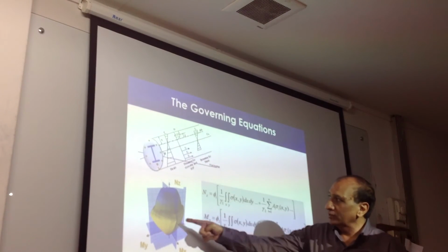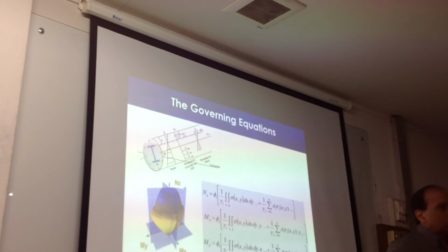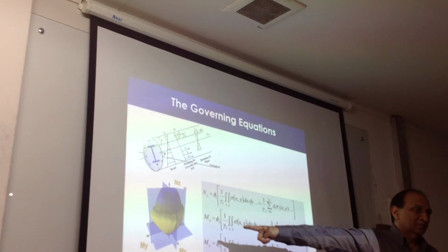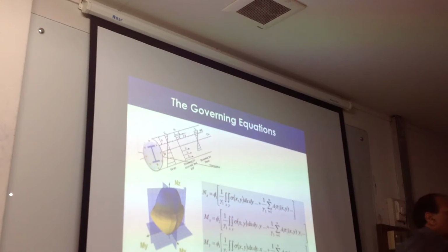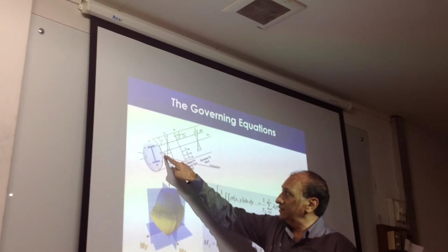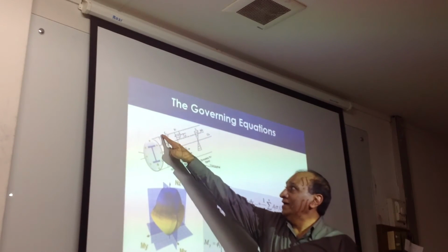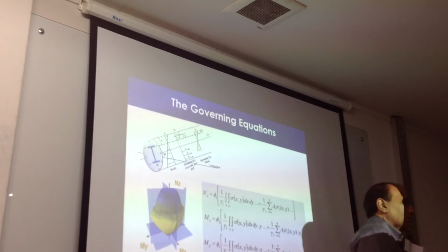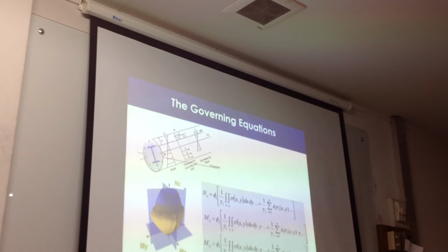This equation can be plotted like that. The outcome of this equation is that surface, what you see over there. So how can we get that surface from this equation? Now, remember, this equation is valid for one angle theta and one depth of neutral axis, whatever it is. Only valid for one angle and one depth. As soon as you change the neutral axis depth, you have to re-evaluate everything. And as soon as you change the angle a little bit, you have to re-evaluate everything.